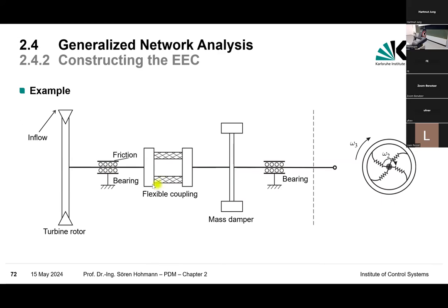So what we can do is damp down these oscillations. And this is done in practice with a mechanical anti-oscillator, which is given here. It's a mass damping system. It looks like this. Here is the shaft, and around it you find a rotating mass attached with springs.